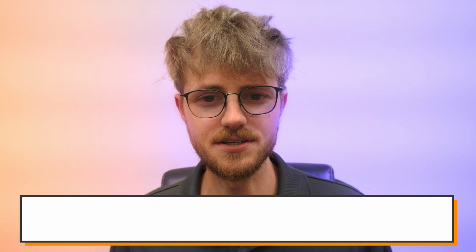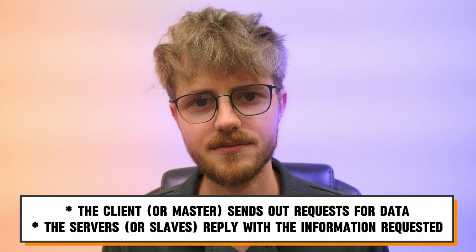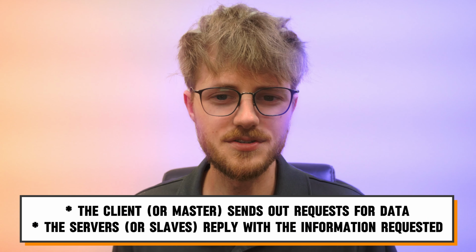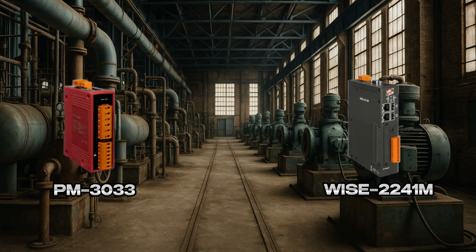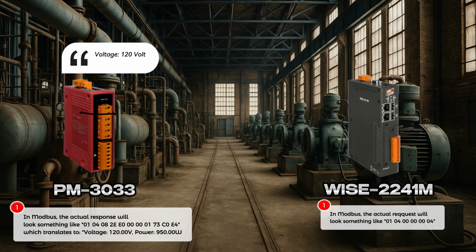Modbus follows a client-server model, sometimes called master-slave in older terminology. The client, or master, sends out requests for data, and the servers, or slaves, reply with the information requested. Here's a simple example. A WISE controller might ask a PM power meter, "Give me your current voltage and power readings." The power meter responds: 120 volts, power 950 watts. And that's it. Modbus is built around these simple, consistent request and response transactions.